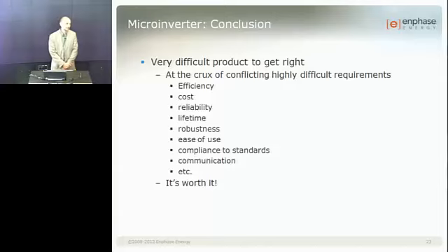So you said that in your predictive control, you only have the input of the voltage balance of input and output, and the desired current. Correct. Don't you need to know the frequency also? No, because I look at it on a microsecond by microsecond basis, right? So the frequency is built in the current I want to get out. In my system, I build an image of the current I want to push out. So at every point in time, I say, what is the current I want now? The current happens to be, of course, a sine wave, which is synchronized with the grid voltage, but this is independent from the power control.